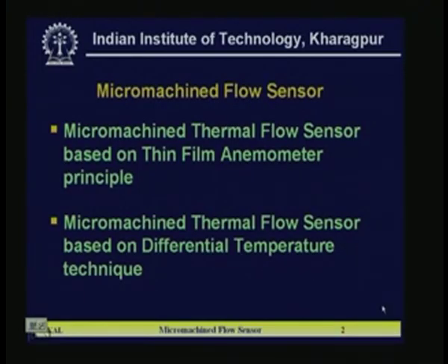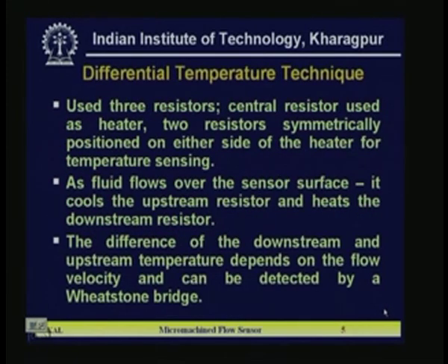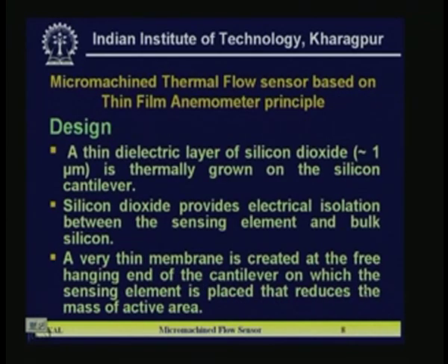Now I will directly go to the design perspective of the thermal flow sensor based on the thin film anemometer principle. In the design perspective, what is to be done? First, a thin dielectric layer of silicon dioxide of 1 micron is thermally grown on the silicon cantilever.